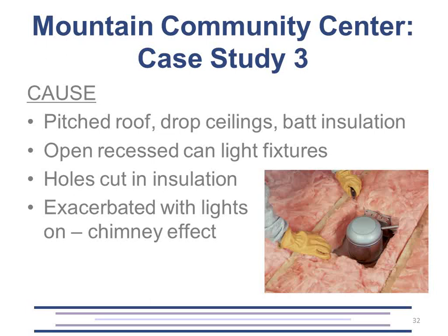Yeah, this picture obviously depicts a closed can fixture. Couldn't find the perfect picture here. It was an open can fixture, and so on the top there it was wide open, and you could see through to the ceiling. Either way, these type of can fixtures have vents in them to allow airflow so that they don't overheat and burn out your ballasts and bulbs, etc. So either way, you're going to get some heat transfer through it, which is why it's important to put the insulation over it.